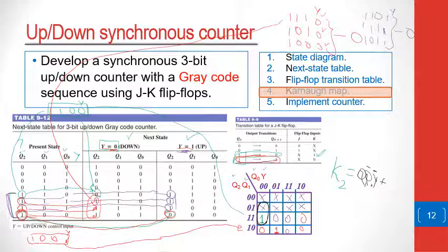So therefore, for this particular case, we have your Q1 remaining as 1, Q0 as 0, Y as 0, plus, here's another group. Another group is this. You see? So in this group, if we move up and down from here to here, we see that Q1 remains low. Q0 is low as well, because Q0 is low here. And Y is 1. So this becomes the input equation for K2.